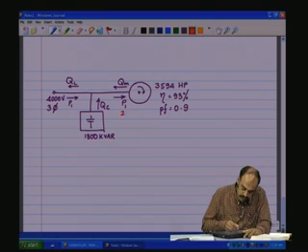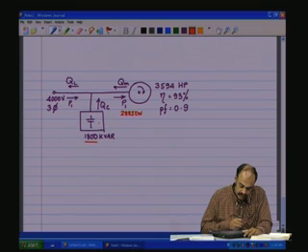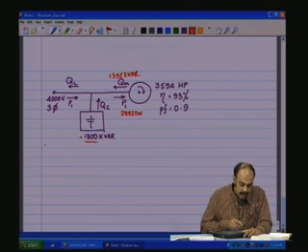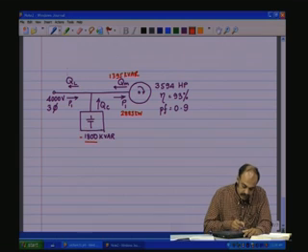this is 2883 kilowatts, and this is having a minus 1800 kVAR. This is minus because capacitive. Now, this is having a reactive component which is 1395 kVAR, and QL is this minus this, and therefore, this is 405, which is capacitive, and therefore minus kVAR.